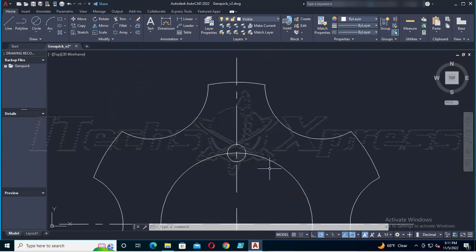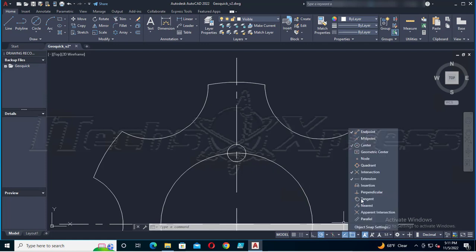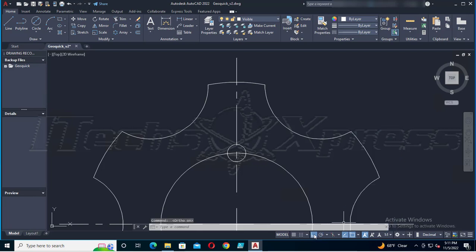So first thing I want to make sure I have turned on is quadrant, and put a check over there. I also want ortho mode on. I could do that even by clicking here and on F8. I'm going to click on line, and I want to go to right there, and then just drag it up. Any as long as it's past this line over here, that's good.